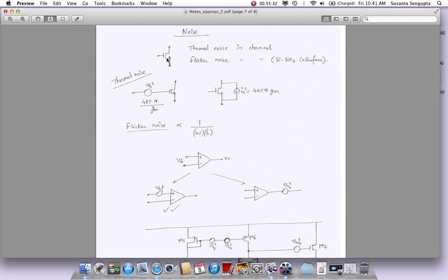Right at the interface, when you have these two different kinds of materials, we have seen in other lectures the silicon lattice structure. We have a certain lattice structure for the silicon, and then there cannot be an abrupt change to the silicon dioxide structure, which is a different lattice structure. So it does happen gradually, and there is a region where there are some extra, unwanted things, like maybe extra holes or extra electrons, because of the transition in this lattice structure.